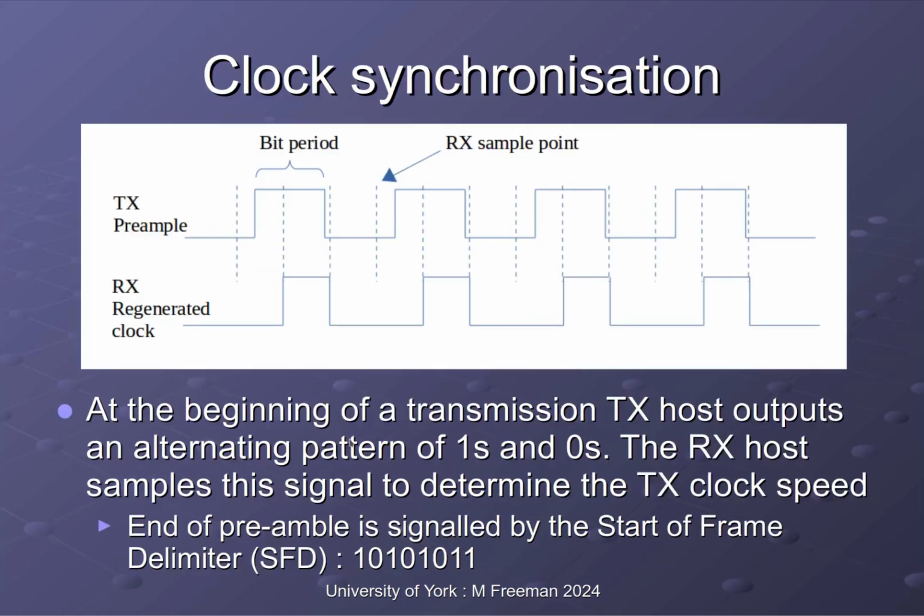So our transmitting end will send down 56 bits worth of square wave. So each transition here is 1 bit's worth of data. And after that amount of time, the receiving end will have synchronized onto that clock rate, so it will know when to sample the data signal.